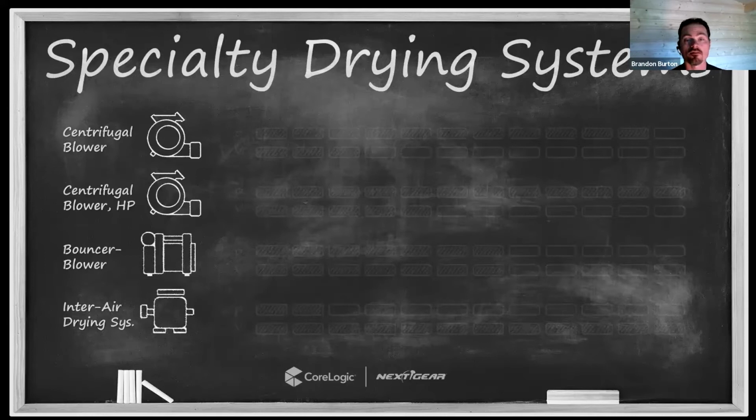If I'm concerned about the cleanliness of the air in the interstitial cavity or space, then we'll reverse that setup. Instead of forcing air into an interstitial cavity or space and out into the living space and then dehumidifying it with my dehumidifiers, we're going to do the opposite. We're going to pull the air out of that cavity in space. We're going to properly filter it or dump it outside. If we properly filter it, we can dehumidify with the interior, if dumping it outside is not practical, right? So just understand, based on the cleanliness of that environment, which direction you want to run these systems we're about to talk about. We can put air in if we're not concerned about the cleanliness, which will generally be your most powerful drying approach. But if we're concerned about contaminants, we want to do the opposite, okay?